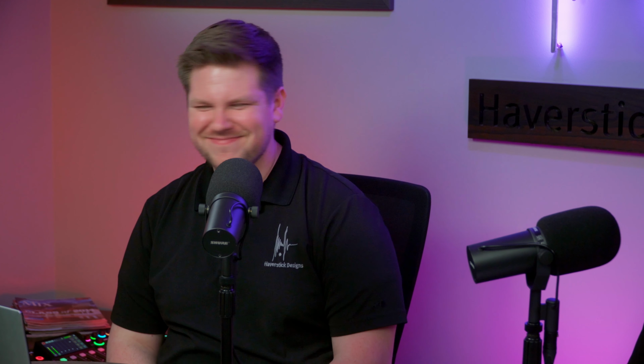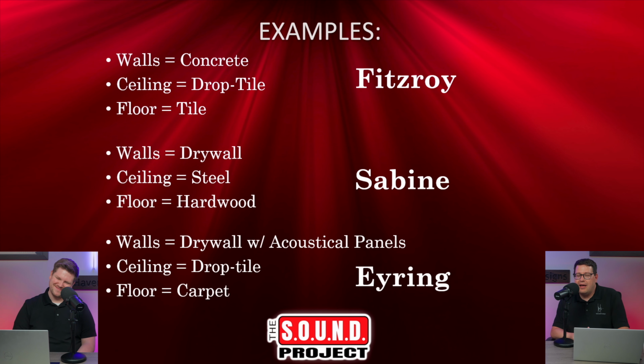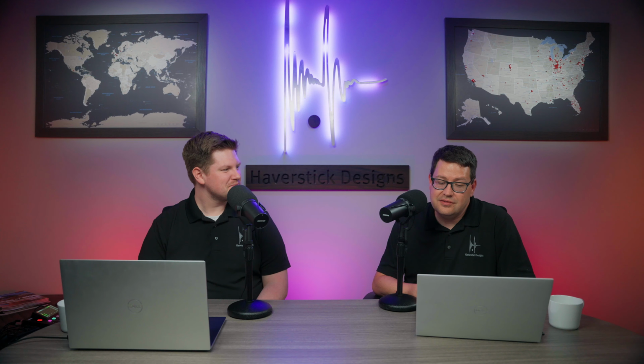All right, so the walls are drywall with acoustical panels. Ceiling is drop tile, and the floor is carpet. That'd be Eyring. Yes, right. You got it. I wanted to have an example for each of them in there. The reason for that is that it's a pretty dead sounding room. It's mostly absorptive materials, and so Eyring would be the way to go.